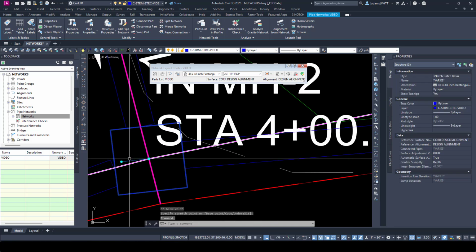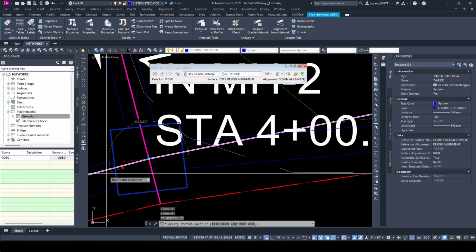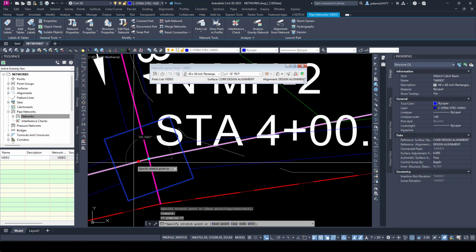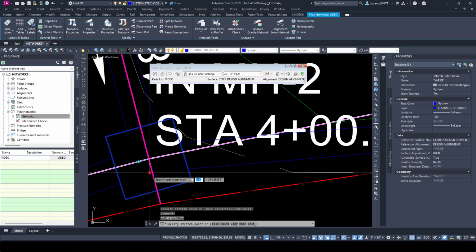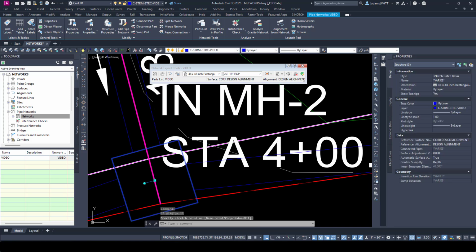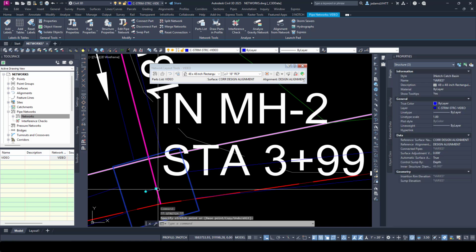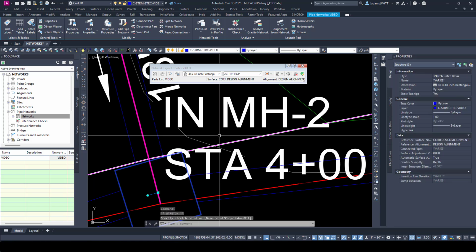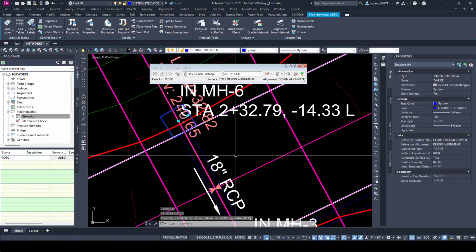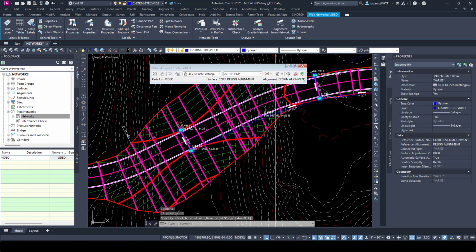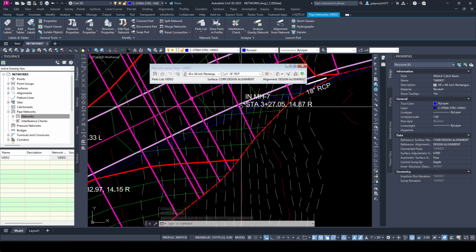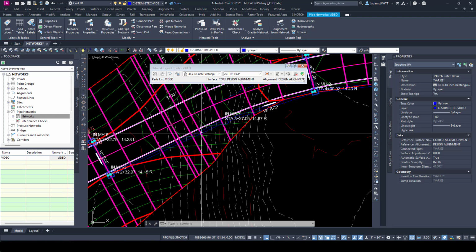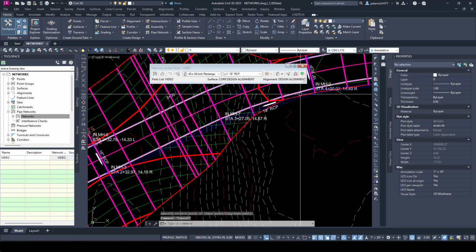So this one, we're going to rotate it, get it more in line with the edge of the road, and then we'll pull it down. And we'll just continue to do that for the rest of these. I'll pause the video so you don't have to see me doing this to all of them. And now we've got all our inlets roughly placed for our round one design. We've got them rotated. We've got them aligned where we want them. So now our pipes are generally right.